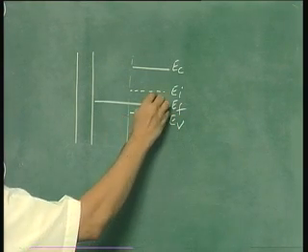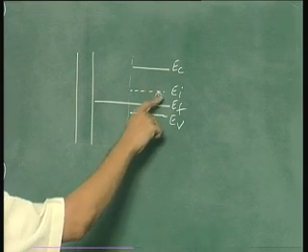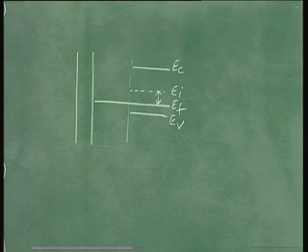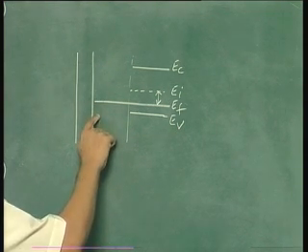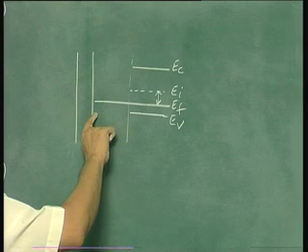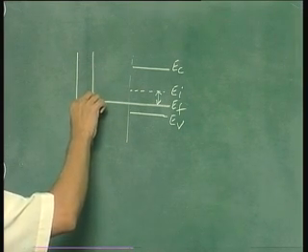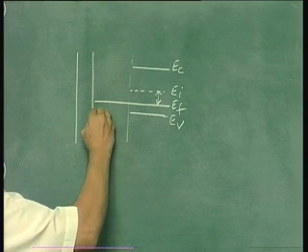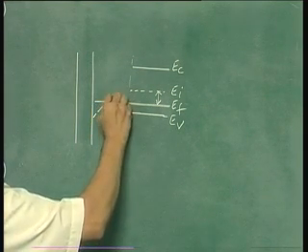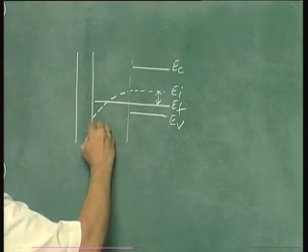And now this difference indicates the bulk concentration of holes, the difference between Ei and Ef. So here your intrinsic level should cross this Ef and come down, so that the surface becomes n-type to the same extent as it is p-type in the bulk. Therefore your band diagram at inversion would be something like this.